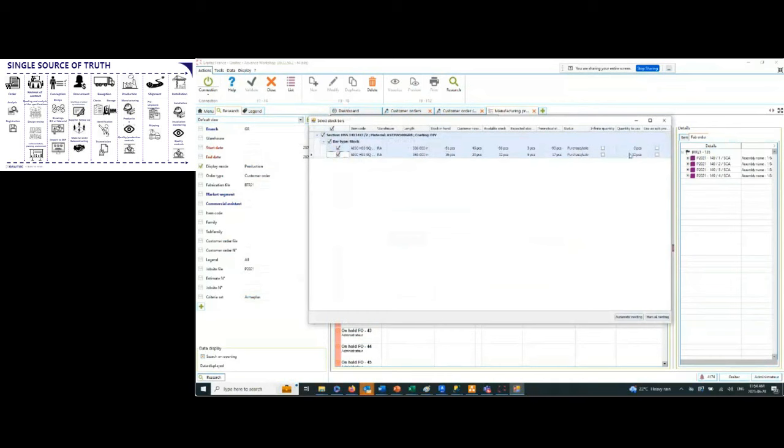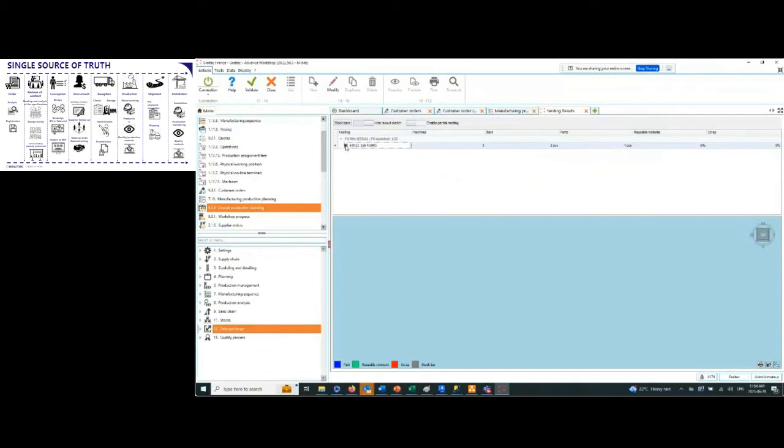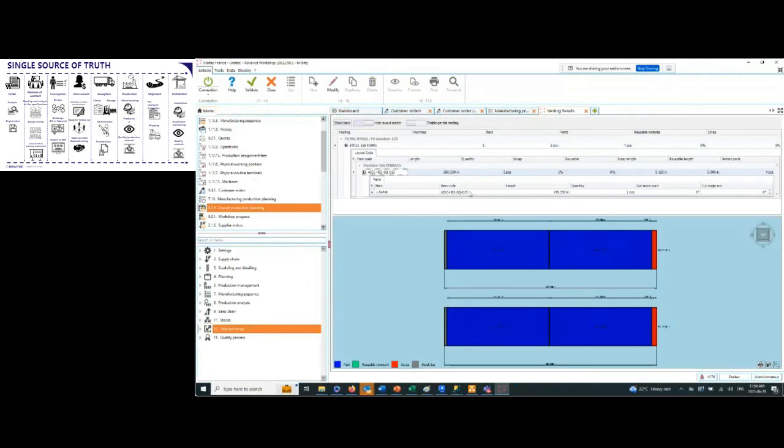regardless of the customer order. Okay, but here I can base this off of an infinite quantity, and then if I use the automatic nesting feature, it'll calculate how many bar elements I need to procure with material waste in mind. So it's going to optimize based off of the SKUs I have available in my system. What this means is when procuring this bar, only utilize either lengths of 20 feet or 30 feet or 25 feet, etc. It'll pull from what's in the system and then suggest to you what will be most optimal to procure.